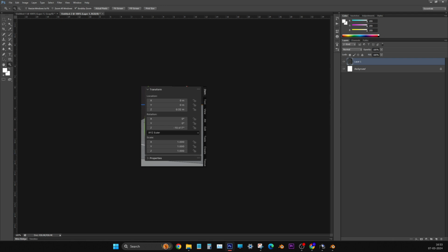Now we are going to that special tool. Make the outliner and properties area a little larger. Now go to this blue color spanner icon in the properties panel editor, where many icons are vertically arranged. Now press add modifier. Remember you have selected the object, and then go to the generate menu. Array modifier. Now you see one is already duplicated.